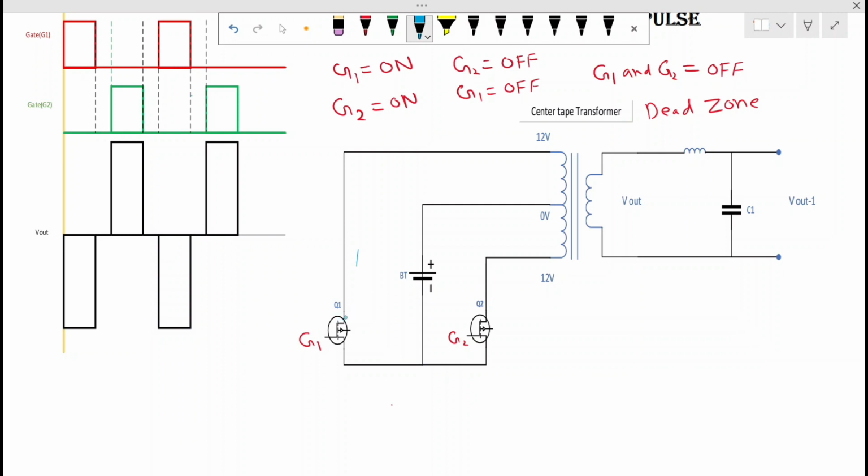Or if it is a transistor, then it is the collector, the positive position you can say. Then the secondary of the transformer is the output, where we get the final output when the transformer action happens by the induction principle, and induction only happens when the switch is operating. In the DC condition there is no mutual induction because flux will not alternate.